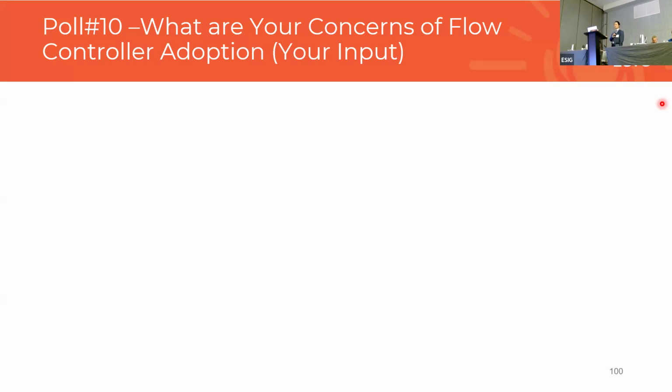Even if you have a lot of imbalance, if your systems are very short and you have relatively beefy conductor, you're going to have imbalance on the system, but you're not going to have all of the manifestations of the power quality issues that come with the longer rural circuits. So definitely in rural applications, especially where you have those long single phase laterals that often wind out there, that's a very clear case for this device.